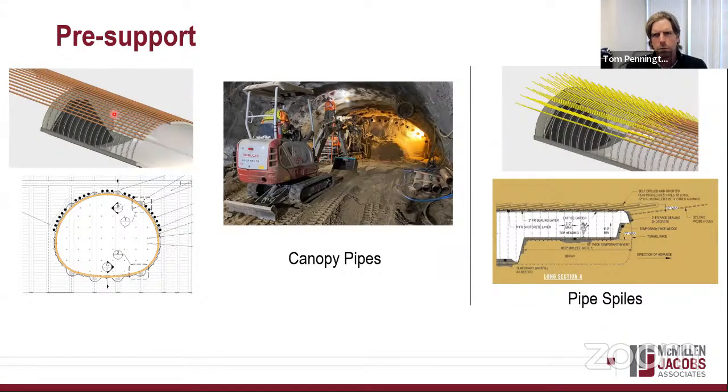Those served as our pre-support for a good section of the tunnel, and then after that we provided pipe spile support, which is shown here in this yellow color in the graphic.